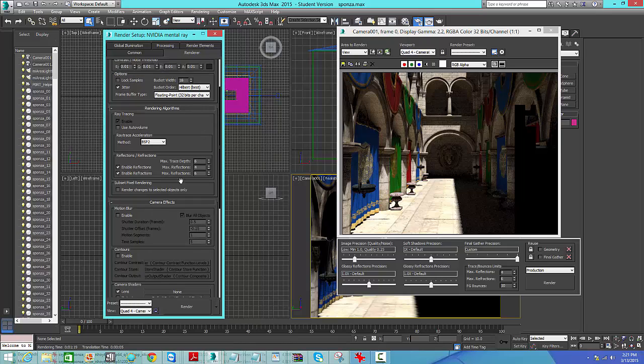So down here are the reflections and refraction settings, and the way these work is this is how many bounces a ray of this type will make in the scene. And it doesn't process them in order. It processes them by order of where items are in the scene. For example, right now this is set to 10 total bounces, but the max depth is only 6, which means that if you have 4 reflection rays, you'll only get 2 refraction bounces after the 4 reflection bounces.